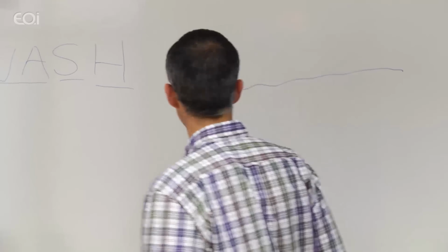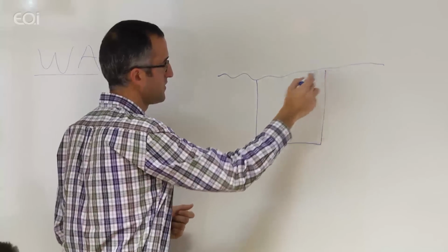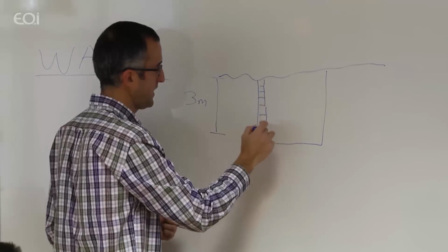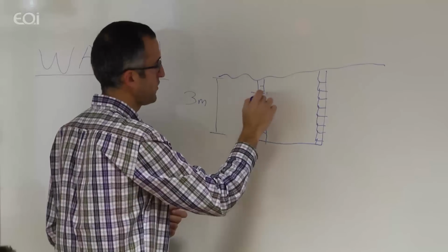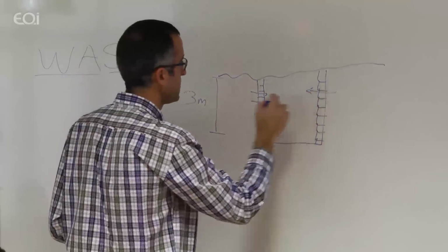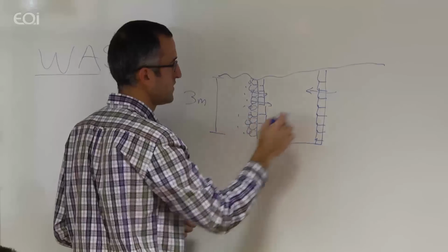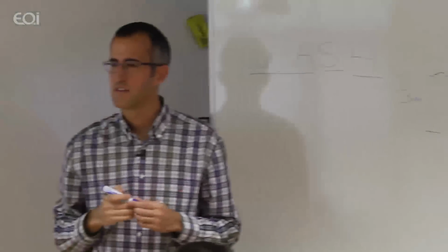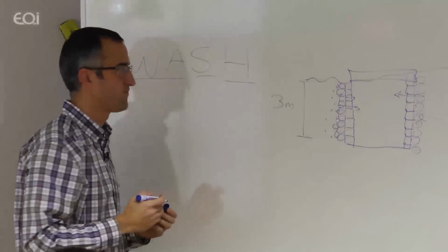you can excavate a traditional well, I don't know, 3 meters, and you can do it like that. And it's important to have holes here, no? But here you can install gravel or gravel and sand, so that you can do an additional filtration. Do you understand? So this is not this example, but a more sophisticated excavated well. And so you have the protection and also the filtration.